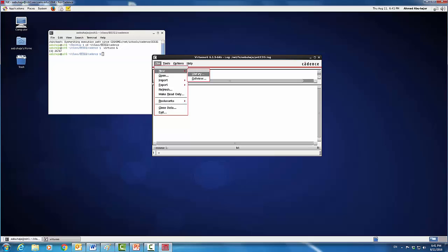Now keep in mind that libraries are the basic mindsets of IC designers. And the reason is that ICs are complex systems, and the way we design our modules and parts is by making them as libraries, and then we can reuse those libraries as we want. Now inside those libraries there are smaller modules that we can use and design and modify, or we can port from other libraries. We call them cell views.